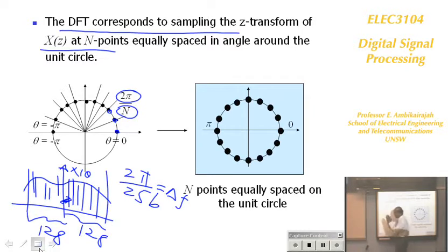If you want very close frequencies to be determined, then you increase the number of frequency points. Later on in signal processing 2, you will find you can't have very close frequency precision because your discrete Fourier transform cannot evaluate it. There is a minimum distance that you have to maintain, and I won't touch on this now, you will learn that later.